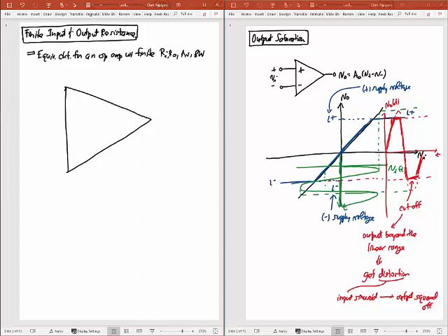I'm going to have a plus terminal and a minus terminal. So put the minus up there, the plus down here. And usually what we do is we just put some terminals here, and we do that because for an ideal op-amp, the input resistance is infinite. Right? This will be V minus, that'll be V plus. But for a non-ideal op-amp with finite input resistance, I would need to put in an input resistor. So I'll call that Ri right there.